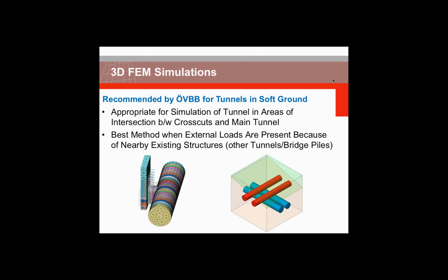This method is also very appropriate when external loads are present because of nearby existing structures, by which we mean other tunnels and bridge piles. On the right side, if you consider the red tunnels as existing tunnels for existing structure, we are designing the tunnels below, which are shown in blue.